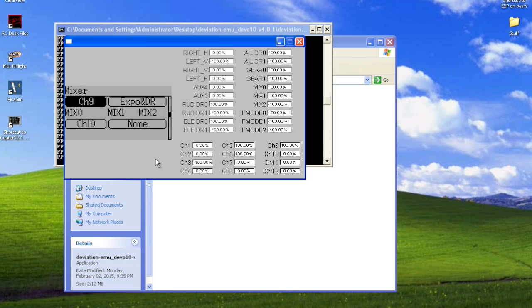I'm not using those here, but they can be set up the same way. You just get to assign the toggle switch. Usually it's something like a trim switch or something like that that allows you to get extra channels out of the radio, which is pretty cool. So again, this mixer setup replaces the entirety of the standard GUI video that I did. So somewhere within this you'll pretty much find everything from that video.